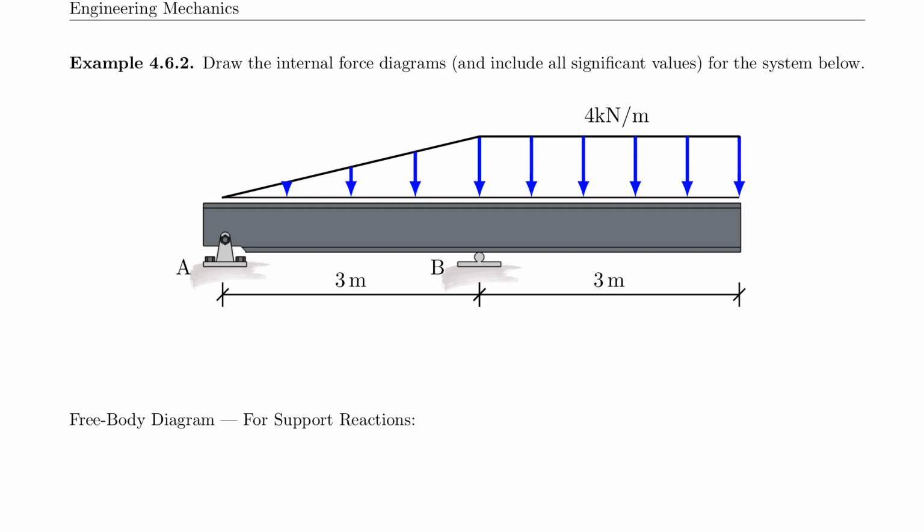So therefore, we immediately know that the support reaction on the left side actually has to pull down, because we have an imbalance that rotates about this point. Think about what would happen if you would remove this support and then have it balanced over this point. Clearly, because you have more load sitting on the right side, it would rotate clockwise about point B. And so I have to balance that. And if you run the numbers, what you would find is that your support reaction at A, again, is going down, but that actually happens to be 4 kilonewton in this case.